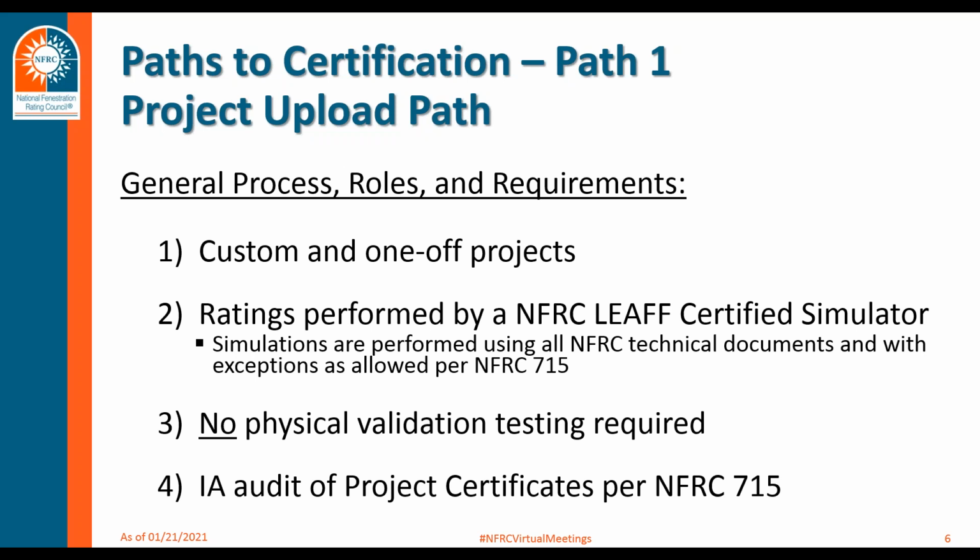This two-step process streamlines obtaining product ratings as compared to past NFRC rating procedures, and is expected to allow for more custom projects to obtain project certificates, whereas they may not have in the past. As stated earlier in this path, only NFRC LEAF certified simulators may perform simulations and submit data to generate a project certificate. The NFRC LEAF certified simulator performs the simulations on representative products confirmed by the certificate requester, and may produce design certificates and final project certificate as required for the project. The LEAF certified simulator is not required to work for an NFRC accredited simulation laboratory.